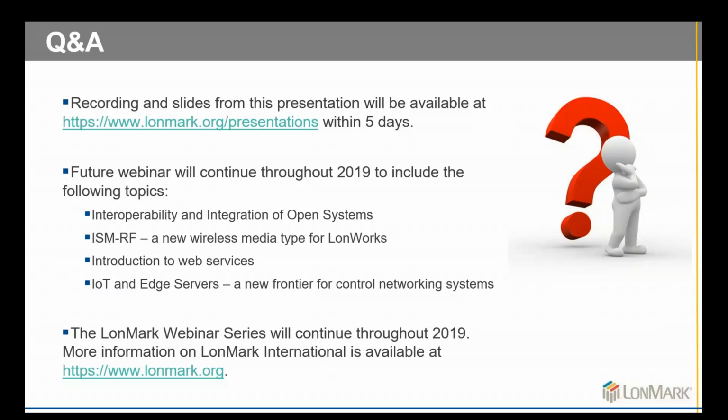Yeah, that's great. I think that leads into the next question. You mentioned that the IEEE standard was initially home application-based. So the question is, does HD-PLC play nicely and interoperate with HomePlug AV and or G.hn? Good question. As part of IEEE 1901, we have what's called ISP, Inter-System Protocol, which allows the different PLC technologies to interoperate. They're not interoperable, but they can coexist. It's a CDMA type of system. So we've solved that problem as long as the other power line technologies support the ISP, there should be no problems.